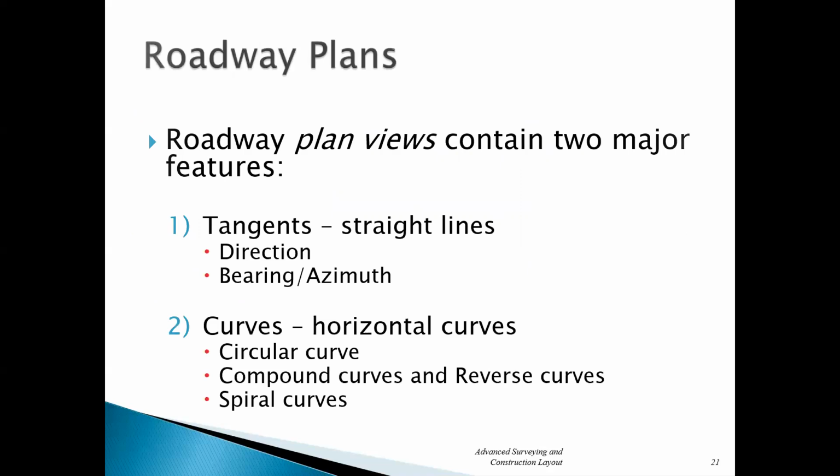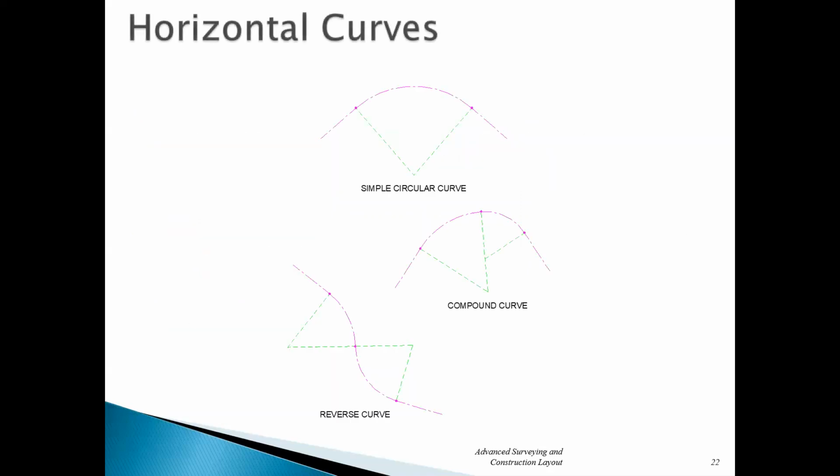That picture is good. So let's jump into the curves themselves. I want to go through this. We basically laid out what was called a simple circular curve. So you've got a tangent that comes into the curve, the curve starts and then it ends, and then you've got a tangent out. That's probably 80% of the highway curves that you're encountering. We talked about some other ones, but we're not concerned with that.